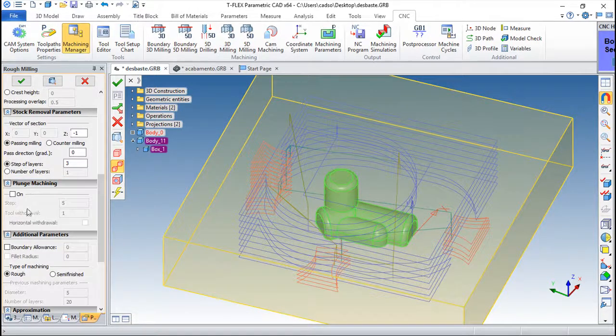And we can turn on also this plunge machining, which mixes the typical roughing tool type with this plunge machining to make a different, I would not say it is better or worse, but it's a different tool type and a different way to approach this roughing type. And we can do steps and define a value for the steps. We can define also the tool width roll, or in angle or doing in horizontal mode.